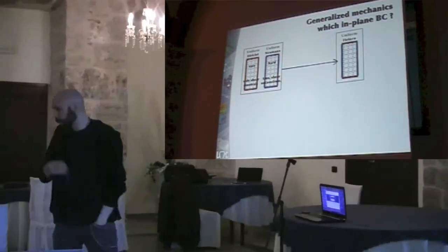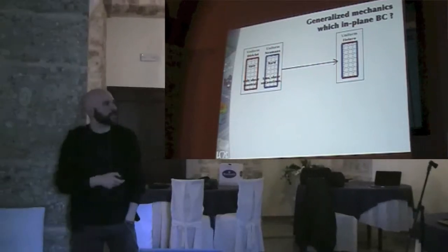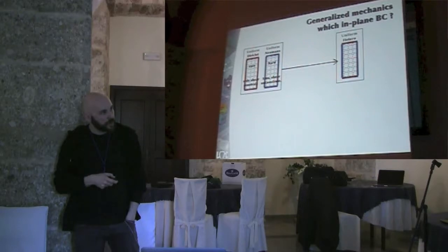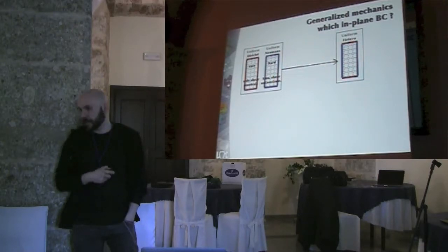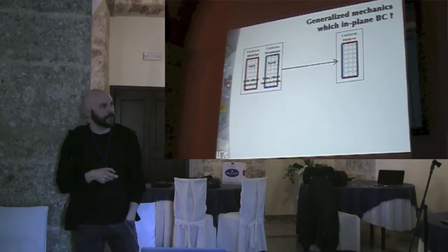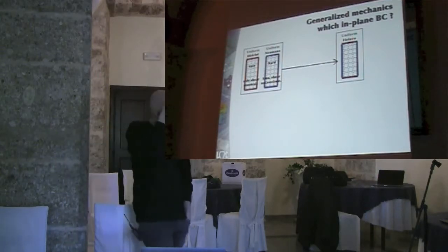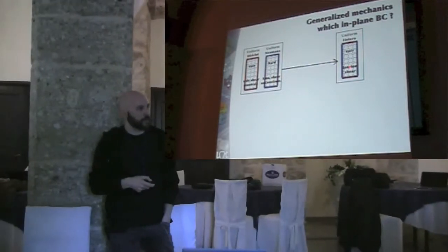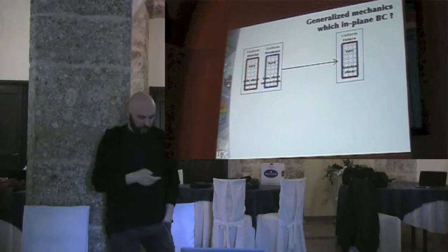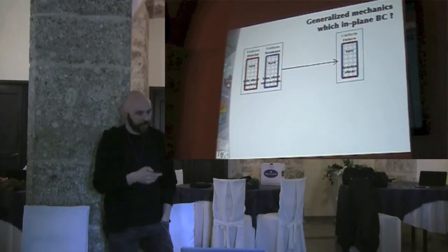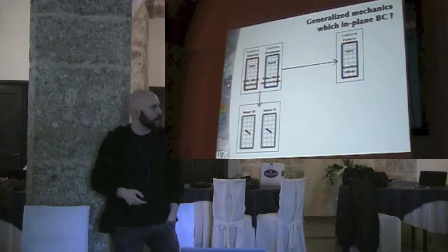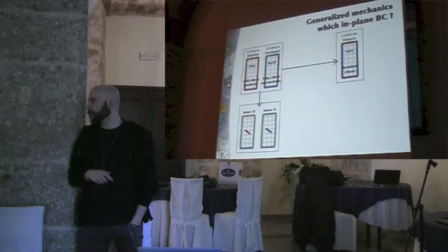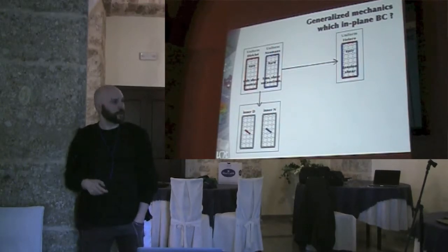What people were doing for standard continuum mechanics were usually uniform boundary conditions, free sides and clamped ends. Okay, so you've got Neumann and Dirichlet there. What can be done? You can also do other things, because this is easy, you can perform tension and shear, but if you want to look at something more complex, it could be interesting to change this boundary condition a little bit. So you can decide to have an inner Dirichlet boundary condition or an inner Neumann boundary condition.